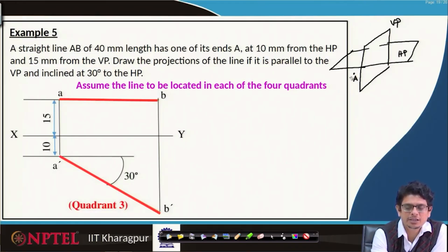That means it is supposed to be parallel to that vertical plane. If that is the case, the way how this line is supposed to make 30 degrees, but it should not intersect vertical plane, it should be parallel to that. So, the line supposed to go parallelly to that vertical plane, but when we are looking at horizontal plane, is supposed to make 30 degrees.